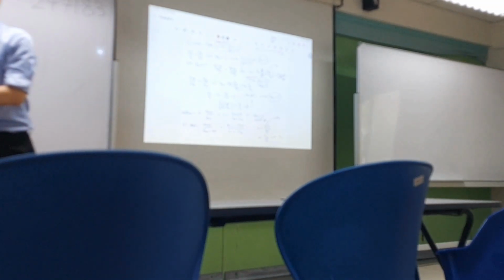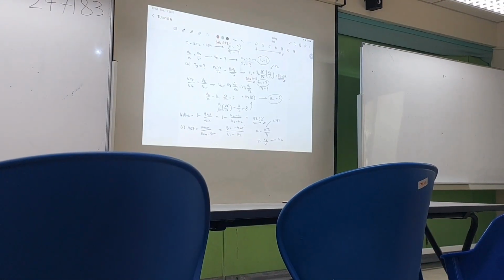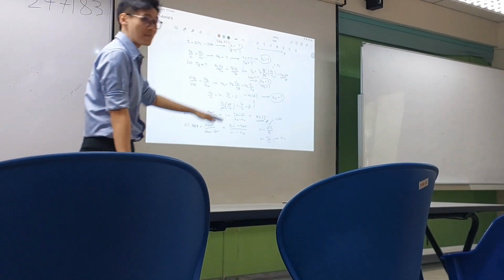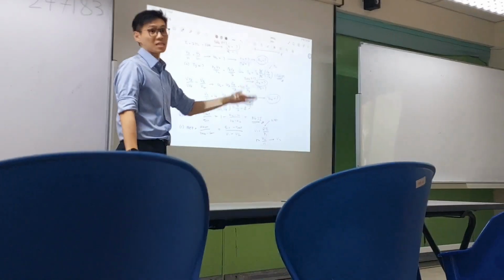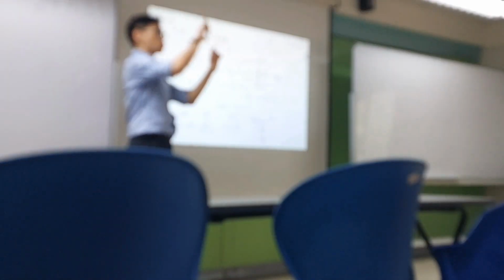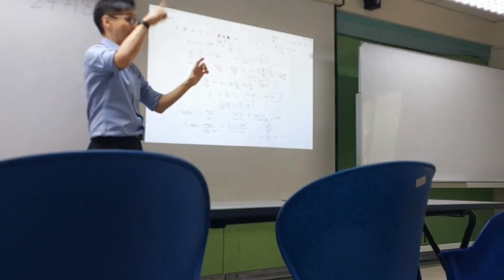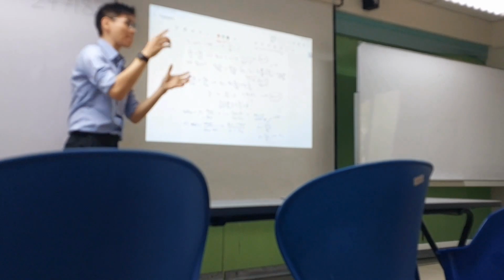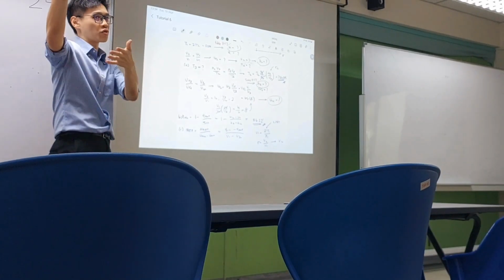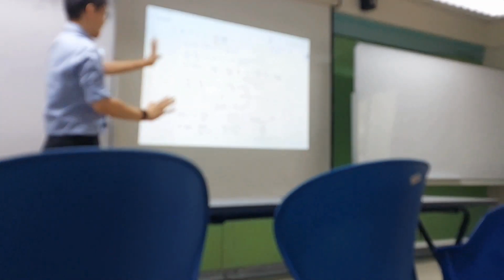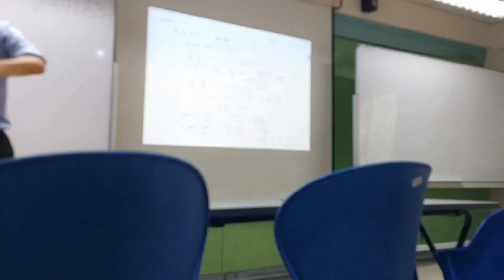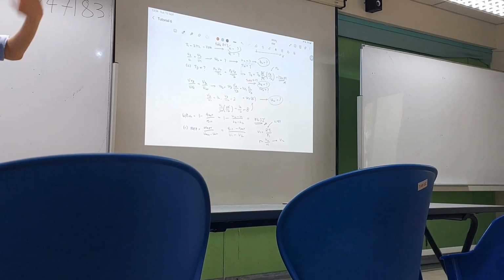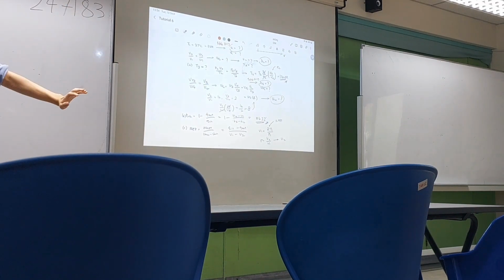For you guys, the cycle, you must make sure that you understand how to analyze them. Cycle has a very fixed way, actually. I'm not saying that every time the question you are solving it based on these steps, but step 1 to 2, 2 to 3, 3 to 4, they have the same type of relationship every time. So the way to solve from 1 to 2, 2 to 3 is different. It's just that maybe I give you different information, maybe I ask you to combine it, go from 3 to 2, you get 1, 2, 3, something like that. But otherwise, their relationship is the same. They have a very fixed relationship. So if it's an isentropic compression, then it's isentropic compression. You won't suddenly change to the other part of the process.